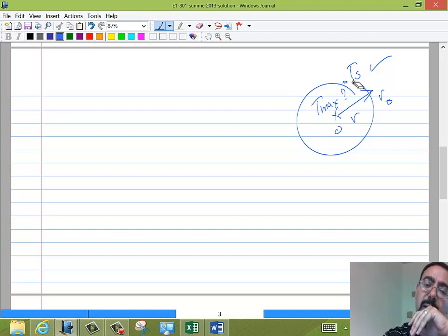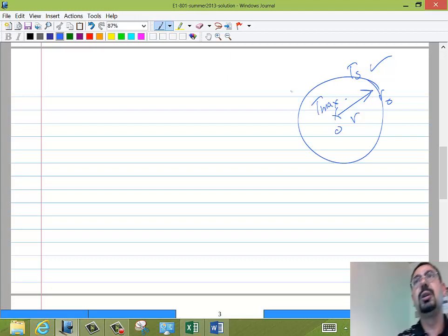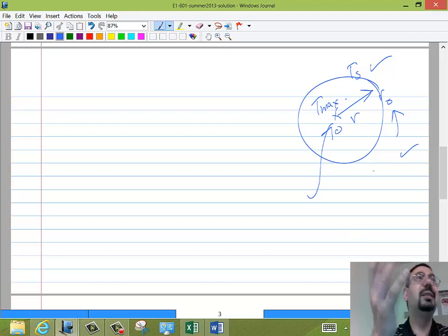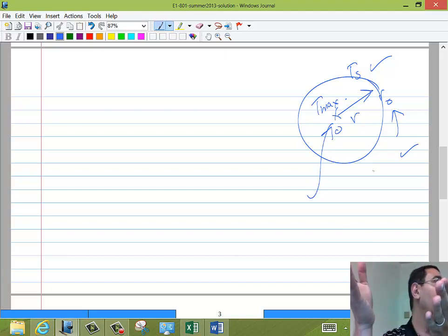So you can start this problem from scratch, meaning you start with the general equation of conduction, you cancel the unsteady term, and you would say, well, I will integrate this equation twice. And when I integrate this equation twice, I need two boundary conditions. One of them is here. The other one would be, where else? I mean, that cylinder starts from r equals 0 to r equals r surface, right? There is no other place to get the boundary condition except at the center line and at the surface.